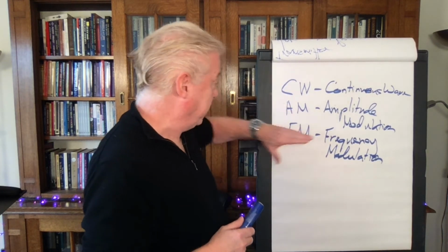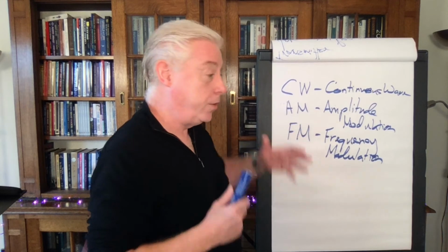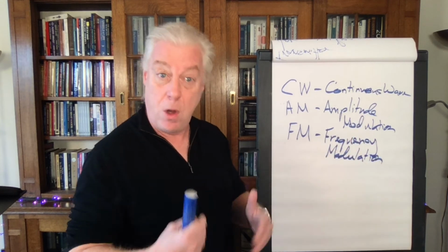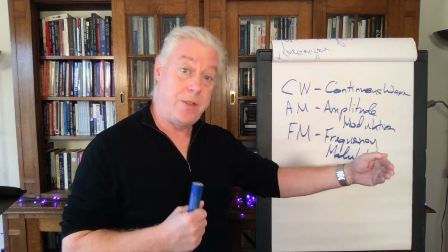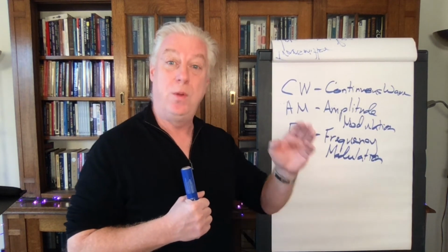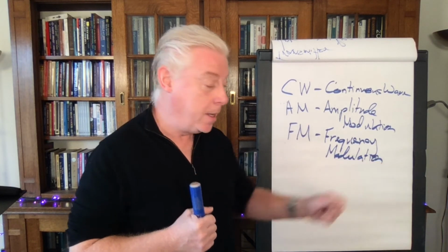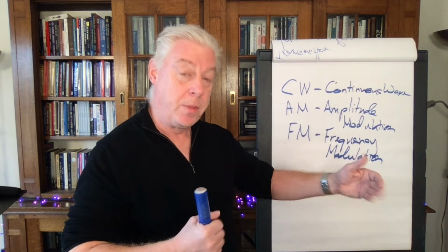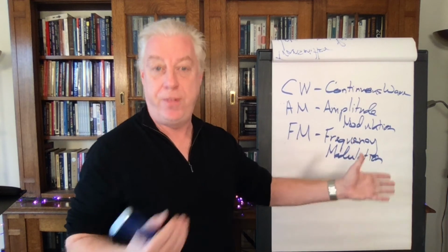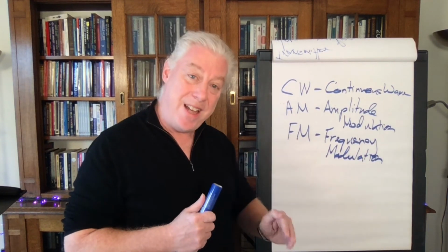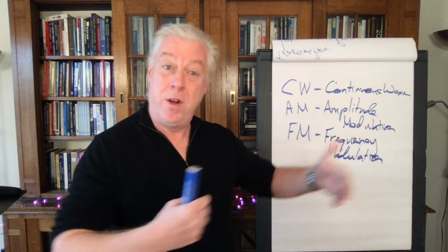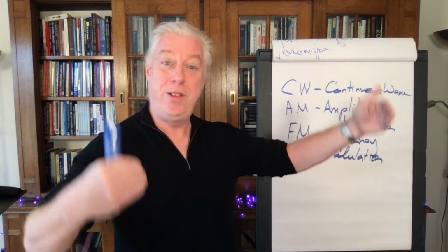So, AM was around 200 to 1600 kilohertz for long waves, medium waves. Short wave broadcasts would be up to something like 30 megahertz. But then we start to get into what's called VHF, very high frequency. So now we can increase the bandwidth, because the frequency's increased. So the FM broadcast band, for instance, in the UK, was around about 88 to 108 megahertz. There was 20 megahertz to play with, whereas the entire shortwave band was only 30 megahertz.